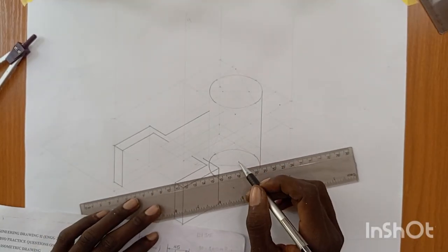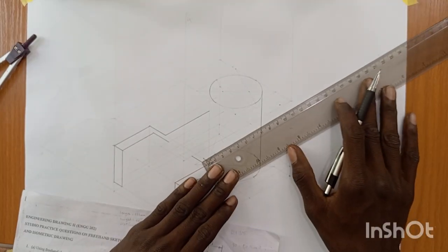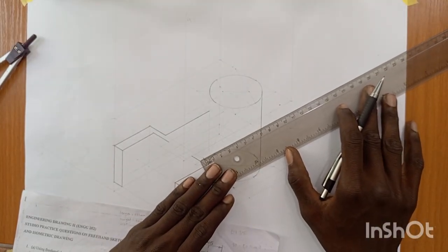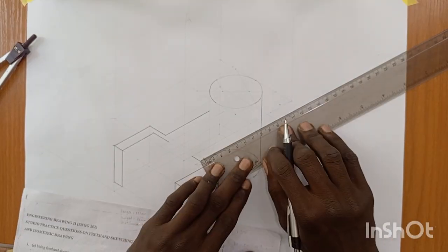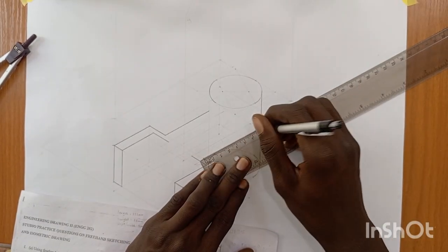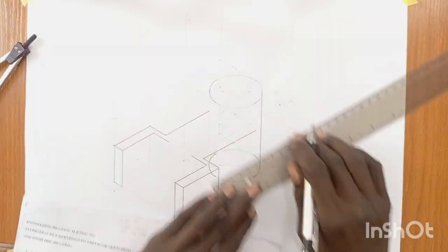So now the next thing to do is to draw this line, also extend it inward of 65 millimeter. So now you measure from here. You're going to measure 65 millimeter. This is 65. Then you can make it darker from the 65 points. Make it dark like this. Okay. So this is it.